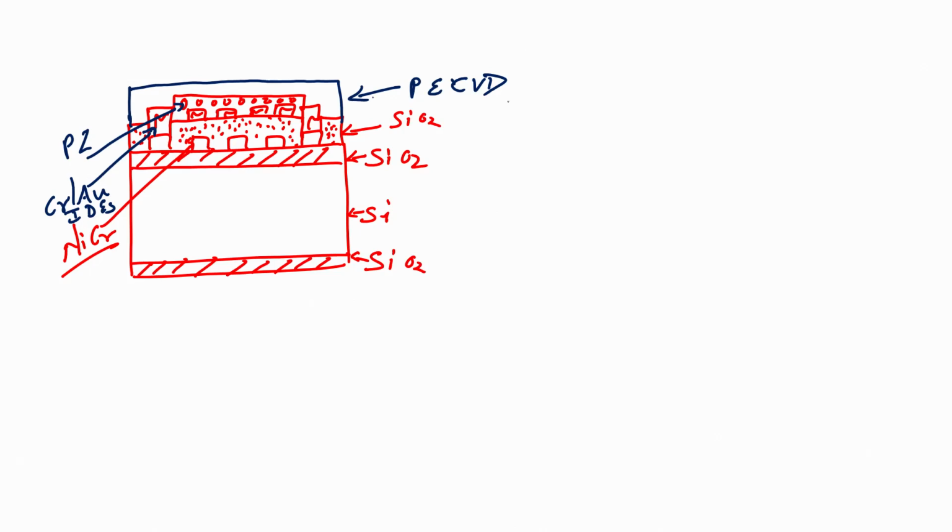Now, PECVD, so that means we have silicon dioxide. Now, what do we have to do? We have to open the silicon dioxide, or open the contact, which is this region and this region, and we have to protect the remaining region. For that what can I do? I have to do a lithography.